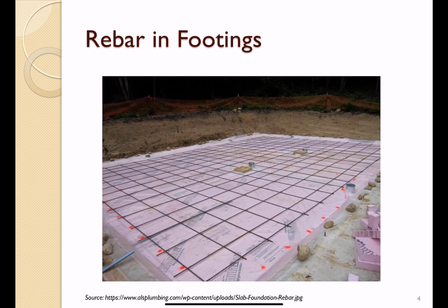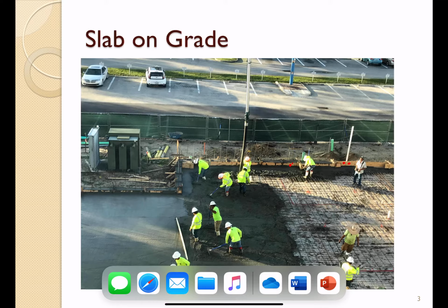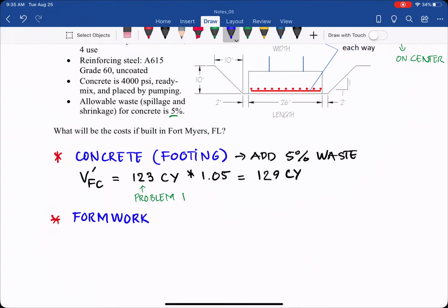I will show you the project done in Homso, the construction method lab next to Homso, back in lot 1, as you can see here. You have the formwork here, but we don't calculate the extra height, only the contact with the fresh concrete, which gives us square foot contact area. And that is what determines the cost, which we will talk about in the next portion of this problem. So formwork is measured by the contact area.